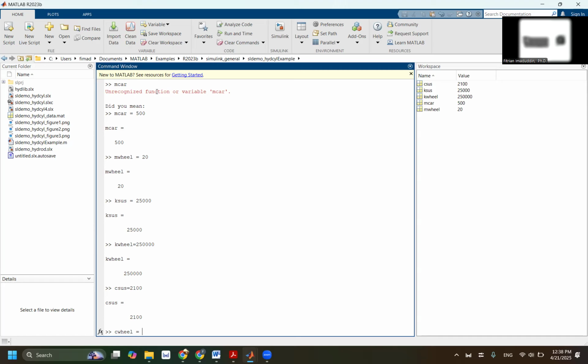But if the damping is really high, it will not bounce. When it bounces, it means you recover some of the energy. The distance between the original height and the height after it bounces is the energy loss. So it's still going to be really in the underdamped region. So I'm going to say if the K of the wheel is 250,000, probably the C of the wheel is somewhere around 10,000. Or make it even less, 1,000.